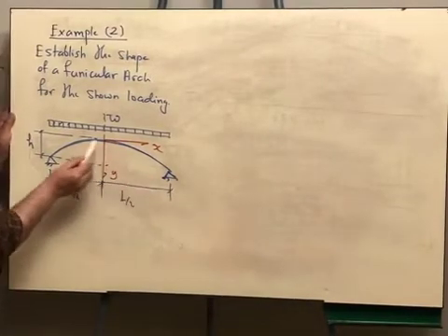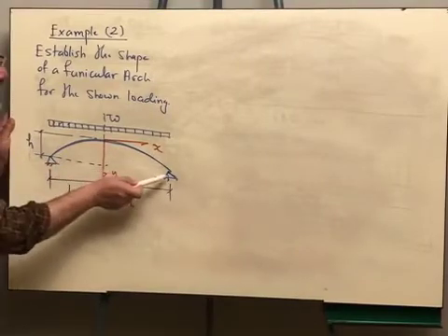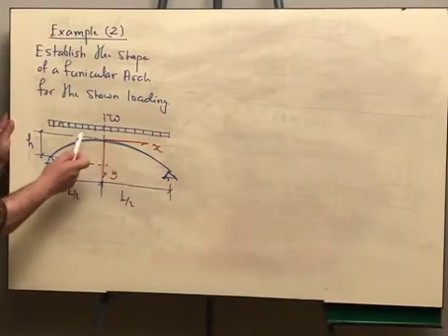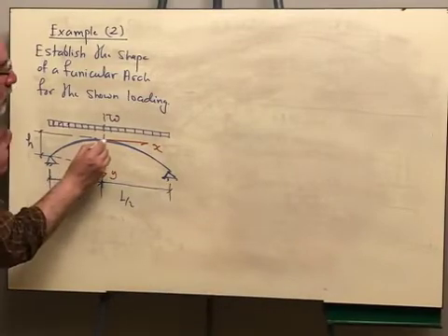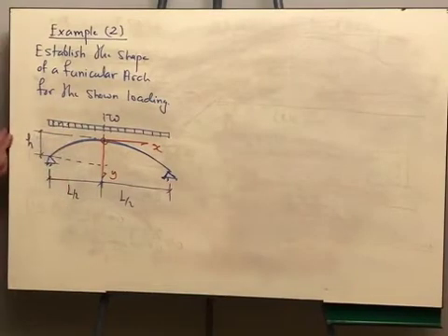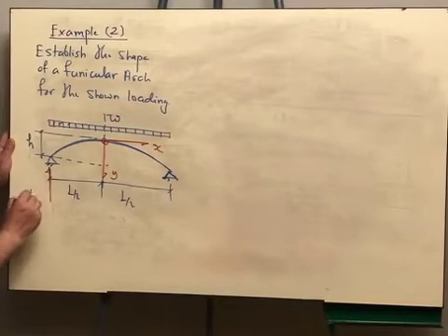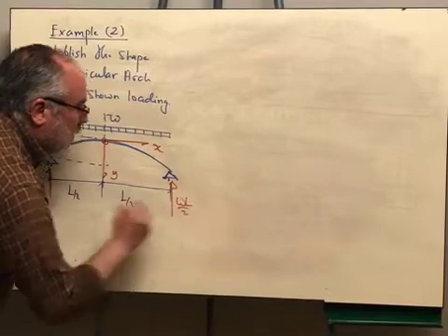Is this curve linear so that it will satisfy that the moment everywhere is equal to 0? Or is it quadratic? Or is it cubic? Or is it of the fourth degree? We don't know. Let us calculate that. Of course, in the funicular arch, all the points are considered to be zero moment or intermediate hinges, so there is no problem that we can assume that we are having an intermediate hinge here. From equilibrium, this reaction would be W L over 2, and this reaction would be W L over 2.